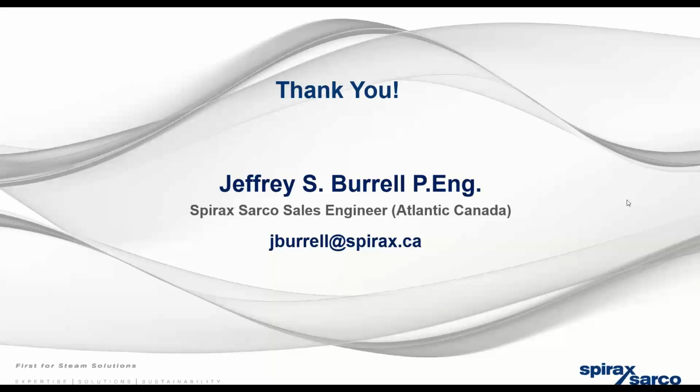Most of the time with flooded heat exchangers, we see a lot of flooded heat exchangers out there that are non-repairable. So the issue becomes, again, as I discussed in the process pressure area, a lot of these systems are designed for radiant heating systems, where my radiant heating systems are on variable volume pumps, to save energy based on outside air temperature, and when I modulate those pumps down, I lose pressure. I could be operating my flooded systems at a very high pressure, and by high pressure I mean relatively low pressure, 80 to 100 psi, and we boil the process water or glycol. It's not good. Yep.